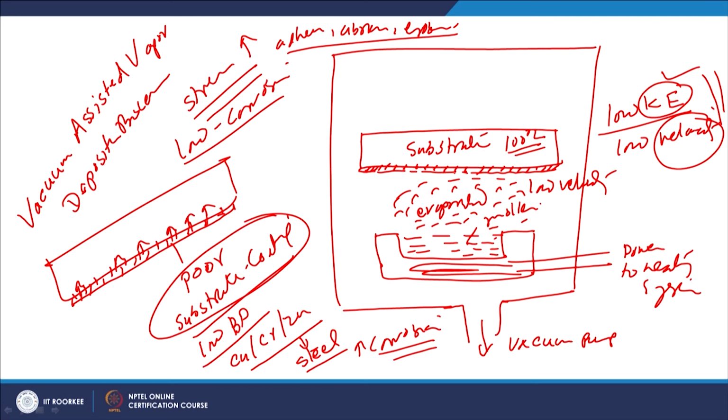So the damage to the substrate in the form of distortion tendency, drop in mechanical properties or microstructural modification, all these adverse effects will be very less with this kind of process, because there is a very minimum rise in temperature. The rise in temperature is limited to 100 degrees centigrade. So there is no thermal damage to the substrate with this kind of process.